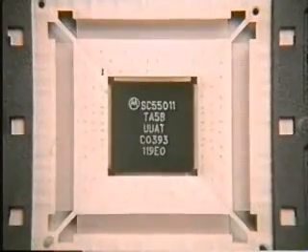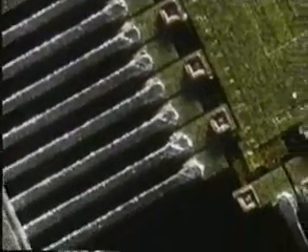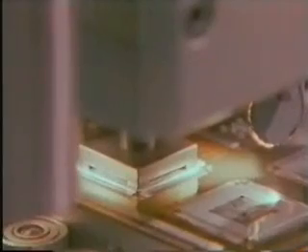Beneath the protective cover and through a microscope, we find the leads attached directly to gold bumps on the bonding pads. This technology eliminates the high inductance created by the thin wire bonds of traditional packaging. Once the chip is cut from its frame, it is carefully aligned for placement. Then, microscopic adjustments are made to ensure the leads line up with the die side bonding pads.